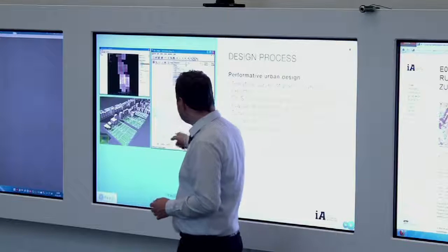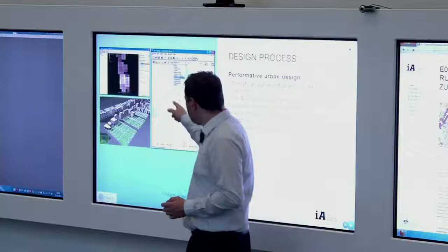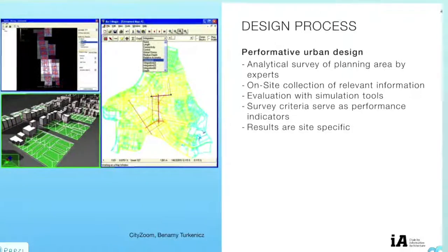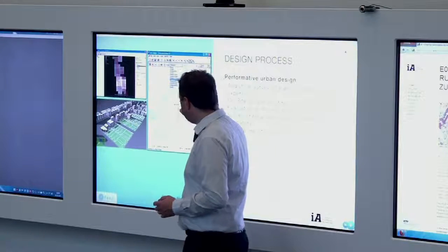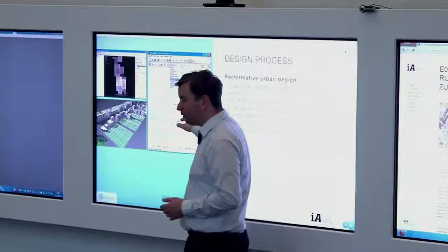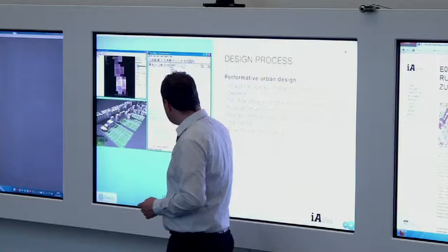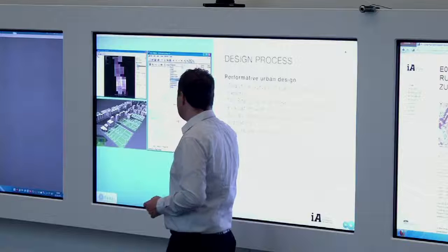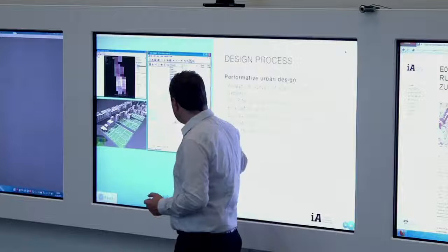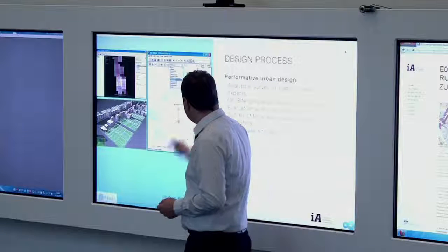Another example, which has been used quite commonly in urban design, is space syntax methods to show the accessibility of certain kinds of streets. For instance, if you select this one here as the main street, here you see the analysis output for all the accessibility, where you can go within a certain time frame, maybe 5-10 minutes. I'm not sure for this one. And you can see how well all the streets are connected to this point. For instance, if this would be like a Broadway, a retail area, you want to make sure that all of the areas of the city are mostly well connected to that area, and that you can get that out as a result with that kind of simulations.